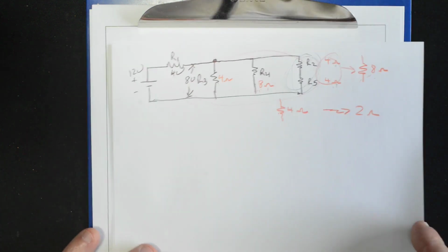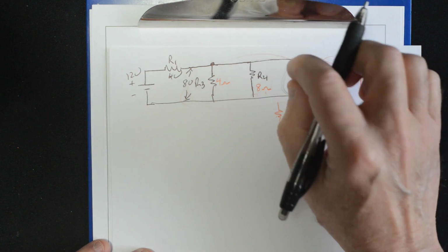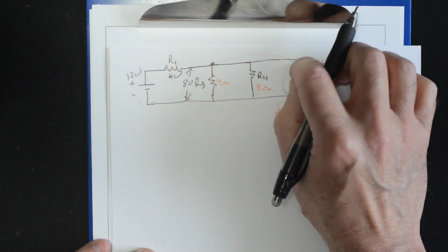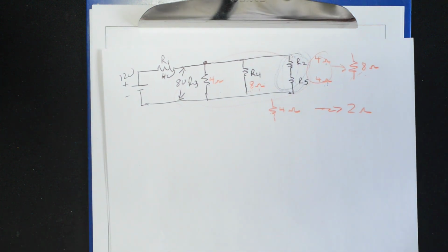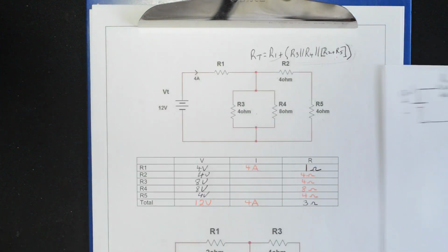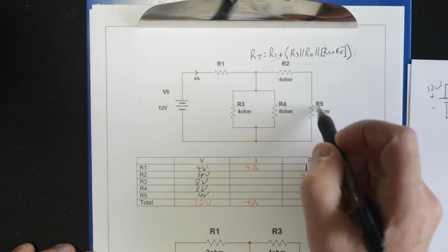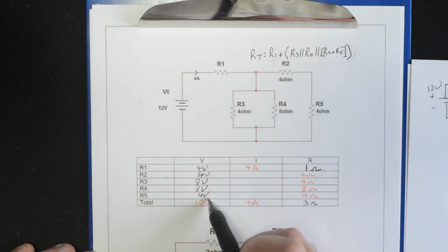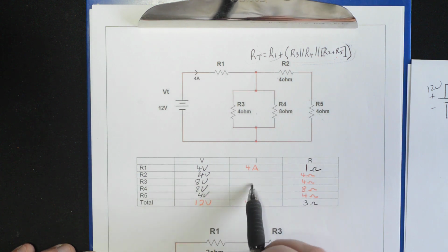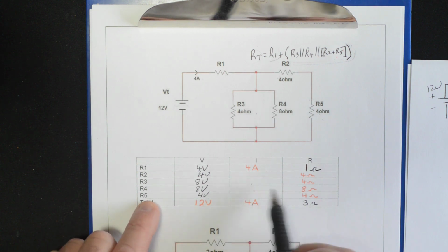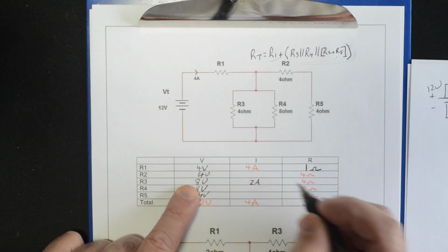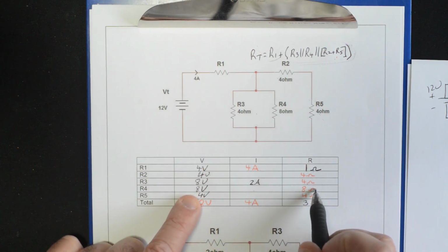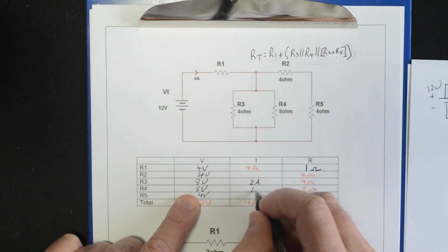Now, if you couldn't take that leap, let's just work as if we don't know this yet. And I'll show you another way that you can figure that out that might be more mainstream, by the book. All right, so let's just assume we don't know what these voltages are, 2 and 5. But what can we do? We can calculate currents of 3 and 4. So what's the current calculation of 3 and 4? So 8 divided by 4, that's 2 amps. All right, what about number 4? We said 8 divided by 8, that's 1 amp.